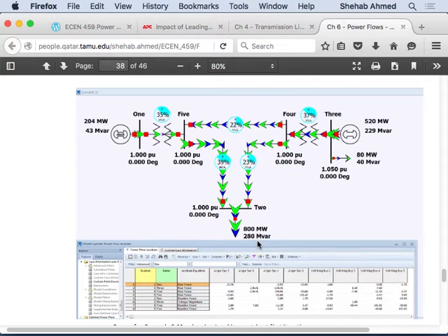Before putting the capacitor, that induction motor was drawing all the reactive power from the utility, right? So there was a reactive voltage drop across the line coming from the generator's side. But now I put a capacitor right across the load, right across the induction motor. What happened?